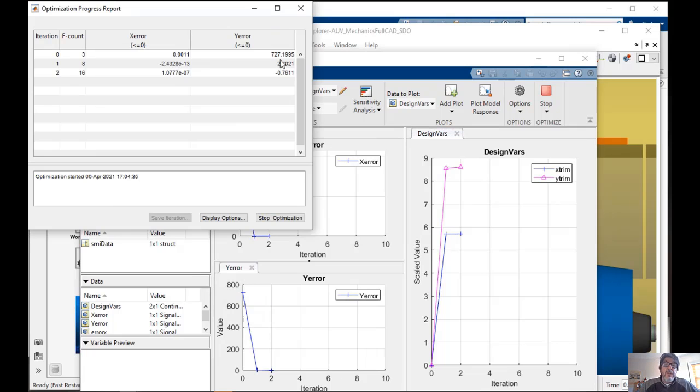You can see the cost function for each one. It's going to run a number of simulations perturbing these variables. It perturbs in one direction, perturbs in the other direction, and figures out, okay, what gets me closer to minimizing the cost function, and keeps on going in that direction. Instead of manually changing the numbers and guessing, this is using an actual optimization algorithm to perform this operation. So you bring your mechanism, and now I can perform a quick optimization problem on that mechanism.